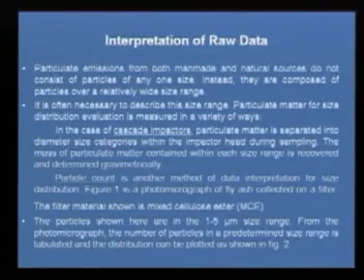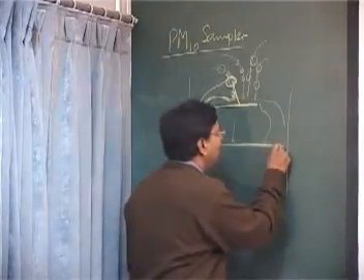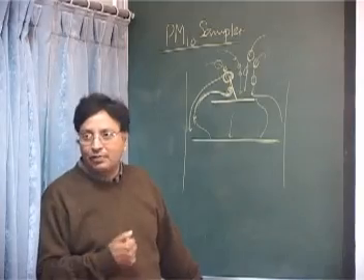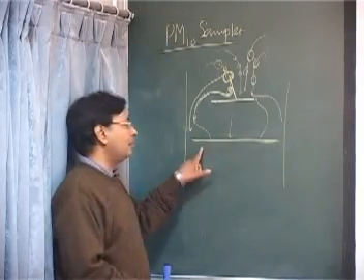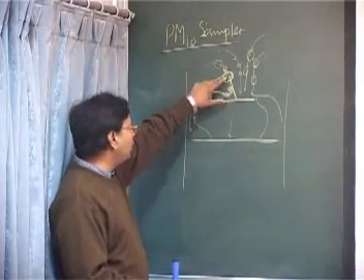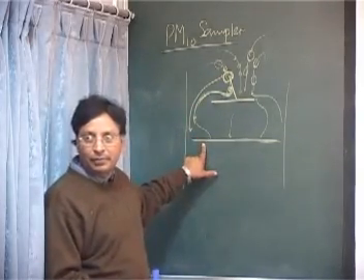Sometimes, suppose you want to find out the metals in the atmosphere. If the filter paper where you are collecting itself has a lot of background heavy metals, then it becomes a little problem, because the background pollution will interfere so much with what you actually want to measure, so your choice of filter paper can be different.